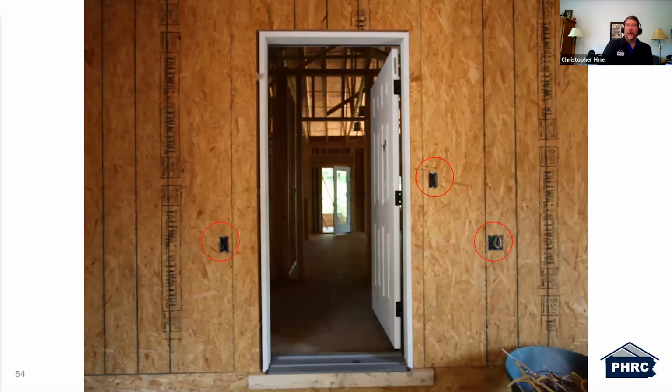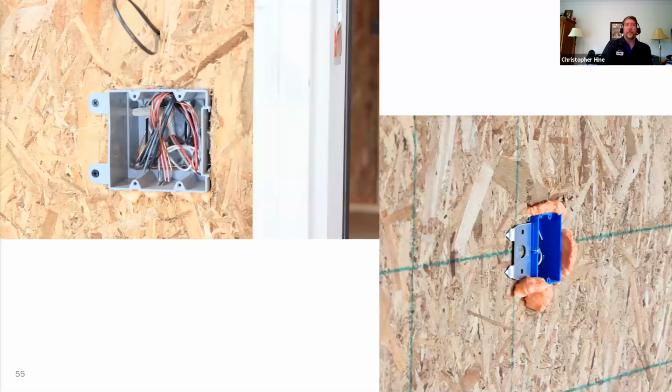But again, you have all these penetrations in that wall. These absolutely have to be looked at as well. Here on the left-hand side, we have the box that does not have any sealant on it. You can clearly see that air will get through there. Okay, this one over here, it's not the best, but it is sealed.